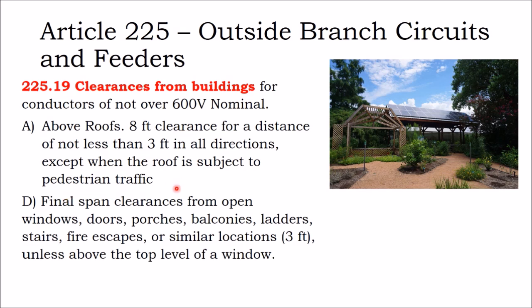The final span clearances from open windows, doors, porches, balconies, or similar locations is 3 feet, unless you're at the very top of the building.